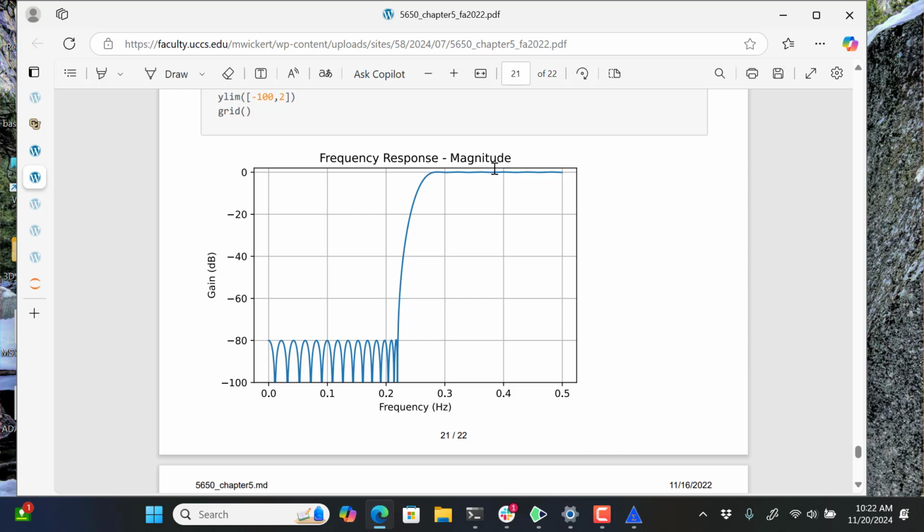I like, myself, the idea of having both views. The pole zero plot lets you understand what's behind it. As an implementer and somebody that wants to get a desired outcome for my system, they won't necessarily be as concerned with the zero locations, but they'd be interested in that. Did we design it? We designed it to get 80 dB of stop band attenuation, and then we set so much ripple in the pass band, and then the transition band was part of the design requirements too, and that's what drove the order of the filter to be so large.